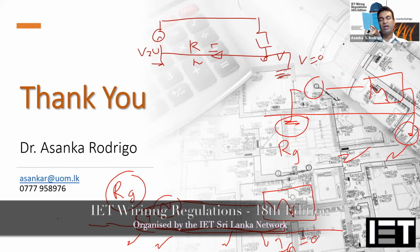That's why, even in the 16th edition and previous versions, certain diversity factor tables were given in the IET wiring regulation, but in the new regulation all of them were dropped, because it's the responsibility of the designer or the electrical engineer to decide the appropriate diversity factor. Okay, understood.